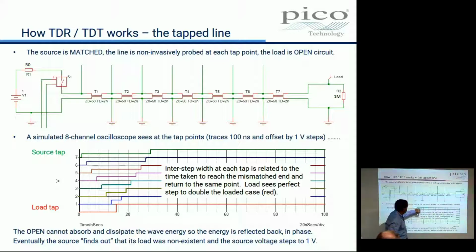If it goes on straight, we had a 50 ohm resistor at the end. If it goes up, we must have an open circuit at the end. Yeah? So we can find faults on cables, and we can find the impedance of things. We can find out if that's a 75 ohm resistor. We can do all that stuff. And if anything went wrong in this cable, we'd see it on here. So it's a kind of network analyzer, isn't it?